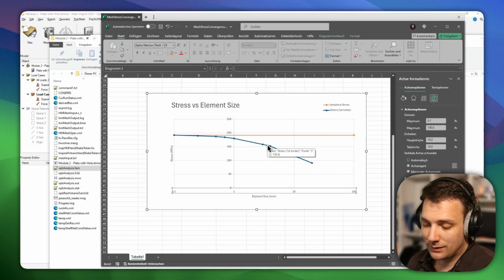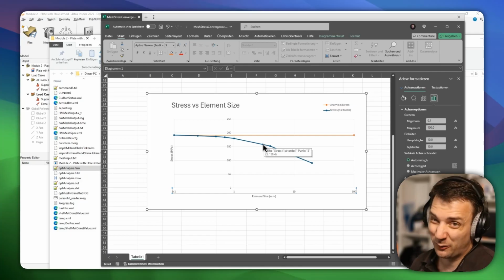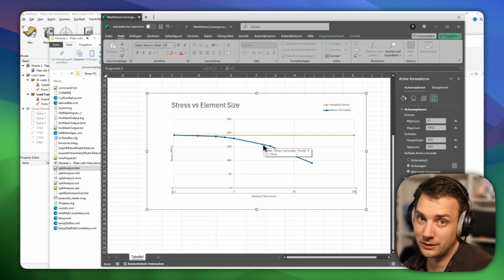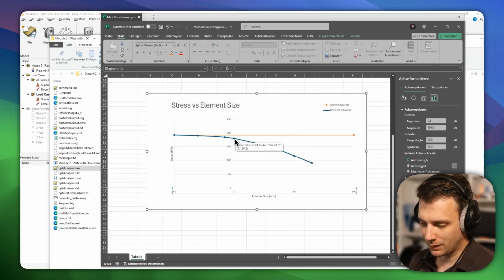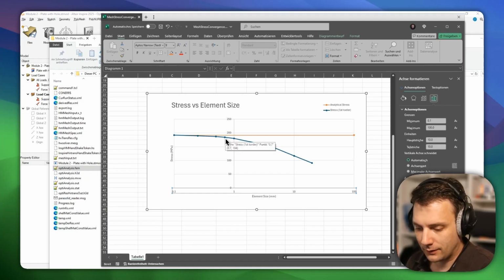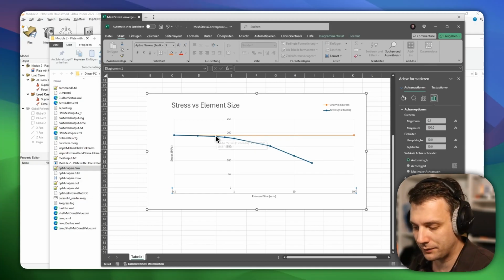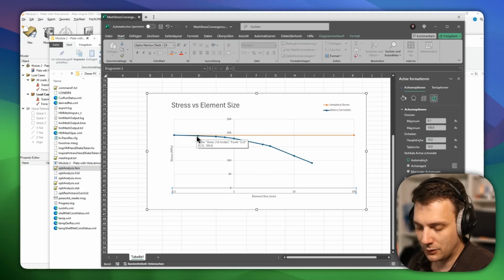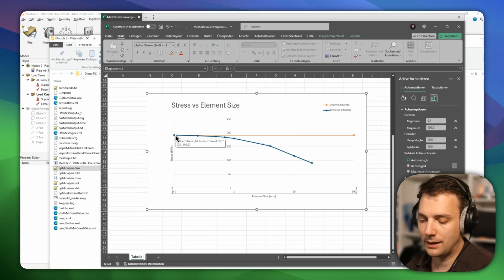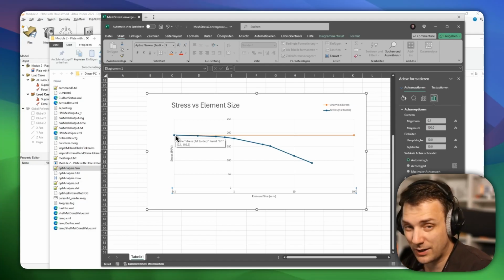Here you could argue, well, it doesn't increase that much, right? From 152 to 158. You could think here that it might converge out at 160, but that's why it's important to keep going. So basically here is the thing for 1 millimeter mesh size, 180. Then 0.7, 184, 0.5, 186. You see, we're not there yet. 192 is the truth. And 0.25 and then 0.1, right? So 0.1 at the minimum element size gets you around the area.